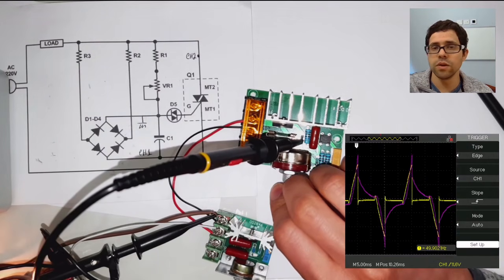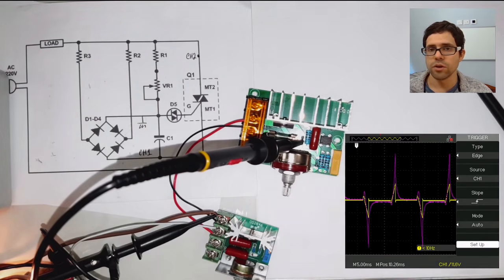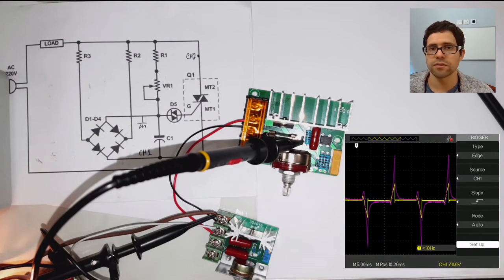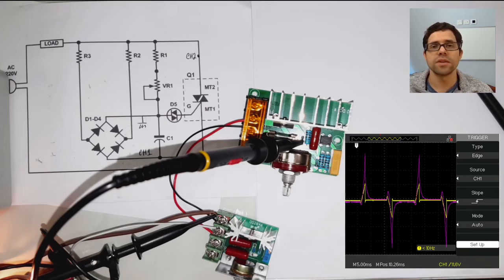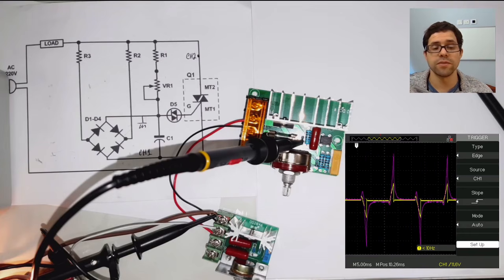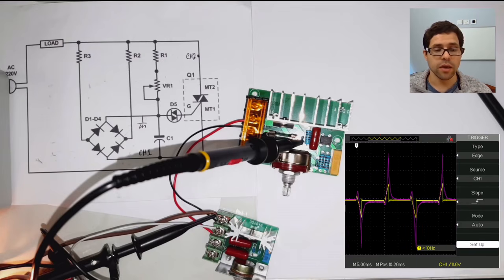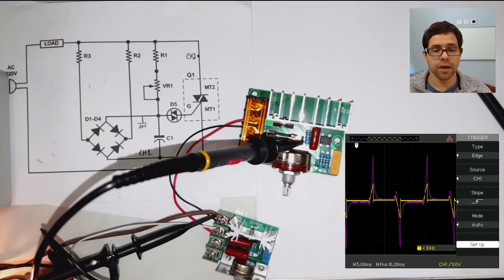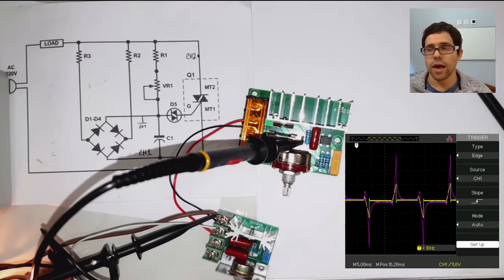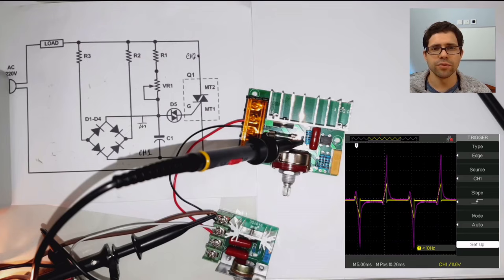Now if I continue to increase the phase angle, we get to a point where the triac is working as an ideal switch and is fully discharging the capacitor across the triac gate, and we start with an ideal condition. And here there's not really a lot of difference to the previous circuit. So this only really works if we are operating at a very reduced output, where we may miss the cycle, or we are operating somewhere half through the cycle.